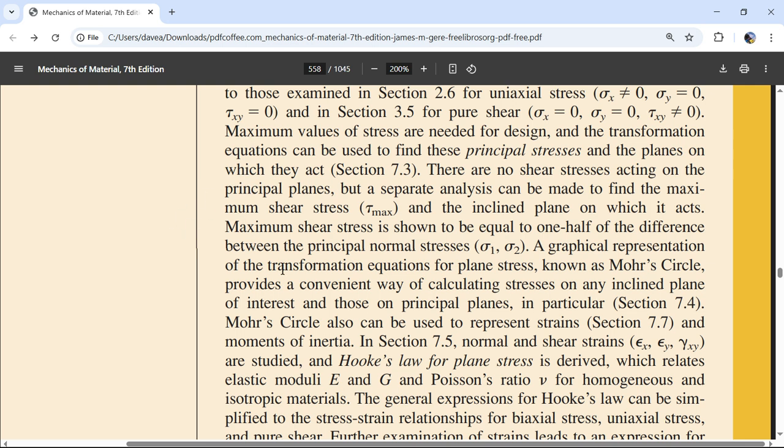I shouldn't say that, because that only happens when something is brittle. If something can elongate up to like 30% max, like steel, it's not going to tear apart like that. But chalk, if you shear chalk, it is going to fail at a 45.